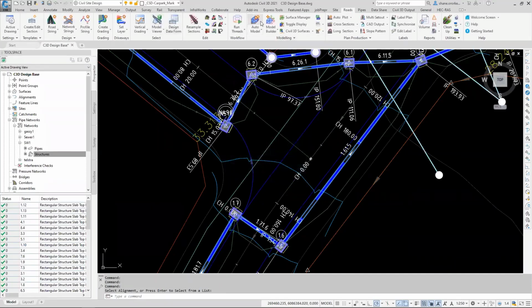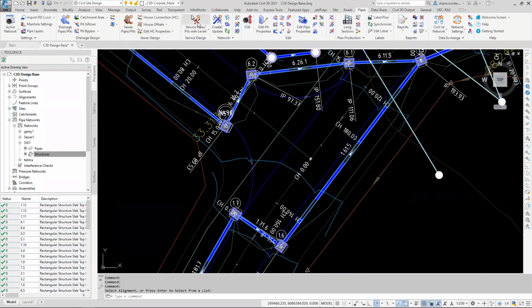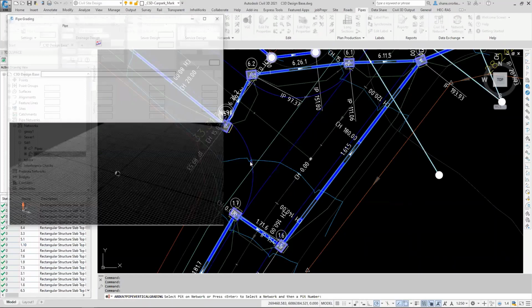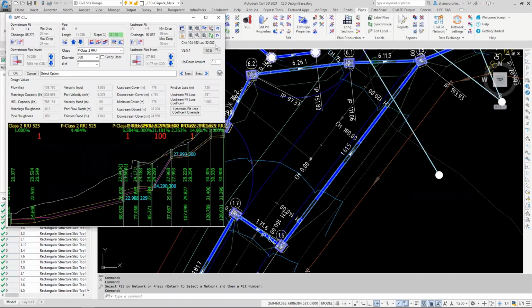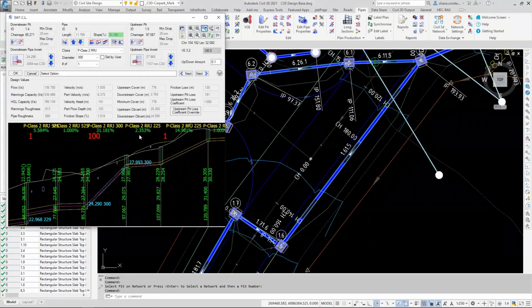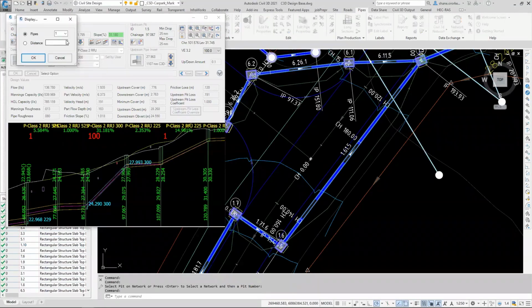if I go to here, sorry, VGE, I look down this network. One of the great things is that you can very quickly do clearance checking straight on the line. This isn't a 3D check, but along this line I can see this pipe has some issues. I'll just get my zoom in a bit closer.